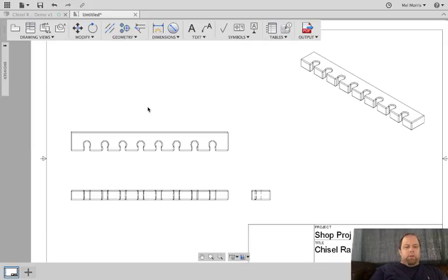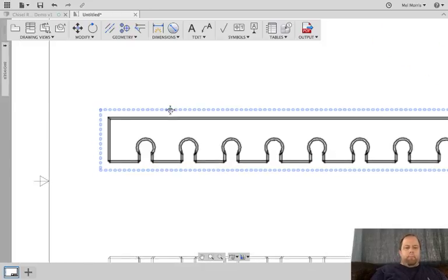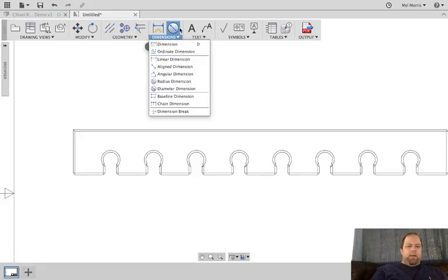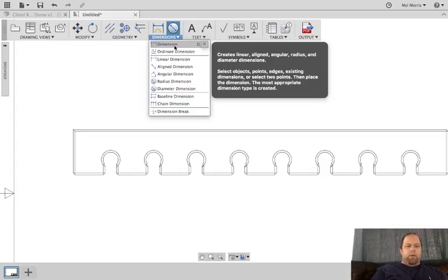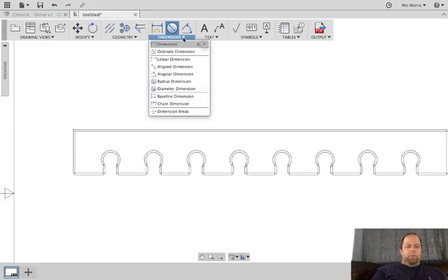Now, when you're dimensioning a hole with a chamfer on it, you have to be sure that you pick your major diameter. So I already have diameter up here on the list. You can get different things populated up here. There's normally, as you go down, I can click up. See that angular dimension is now up there. To get it off of there, I click it off.